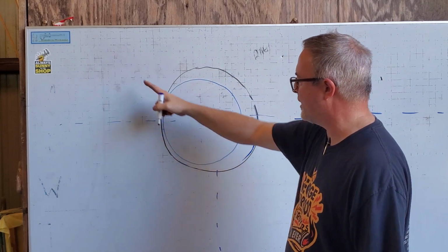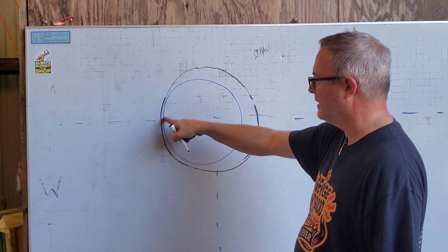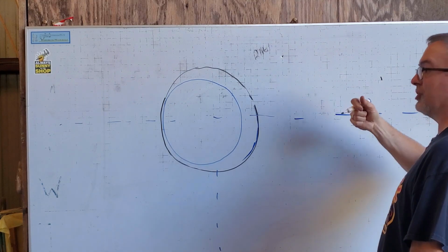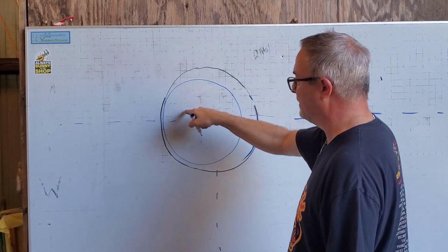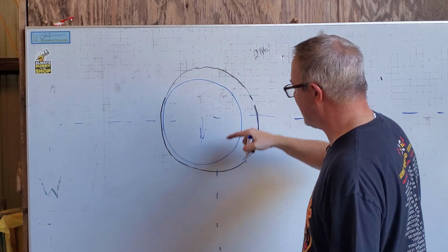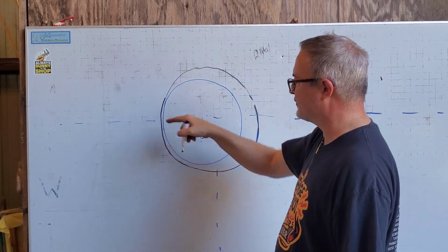Because during this entire portion of the stroke, we're compressing the oil film by the action of the piston, and we're slowing down the piston, so it's pulling on the crank. So the oil film stays here, and as the crank continues on past front dead center, this does not swap sides.